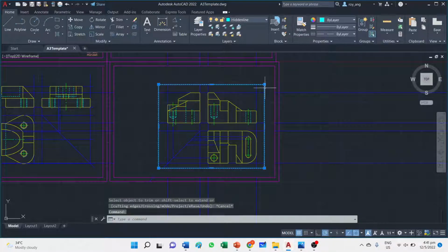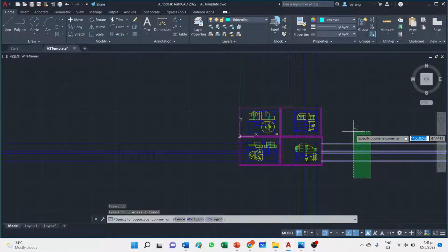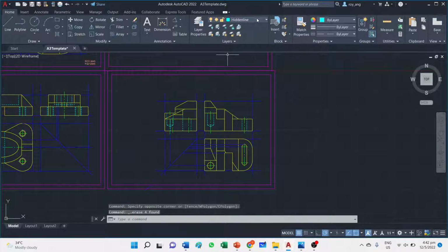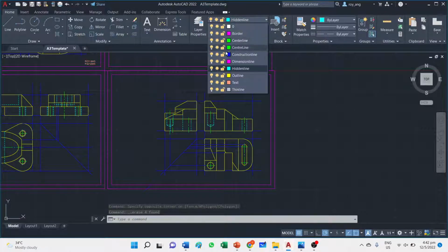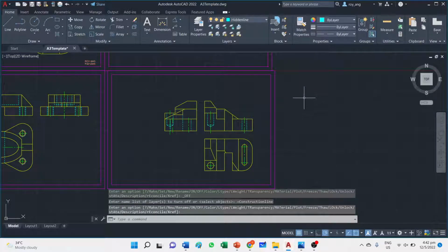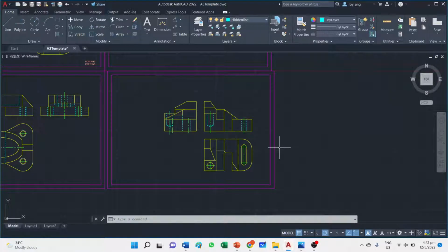And don't forget to remove. Then you zoom out and you select all the infinite lines that are outside of your borders. Okay, and we do a quick check by turning off the construction line so that we can see if we made any mistakes. And there you have figure 3 question 2d.